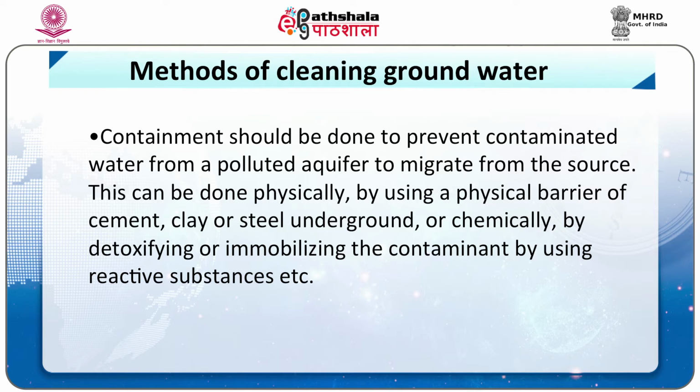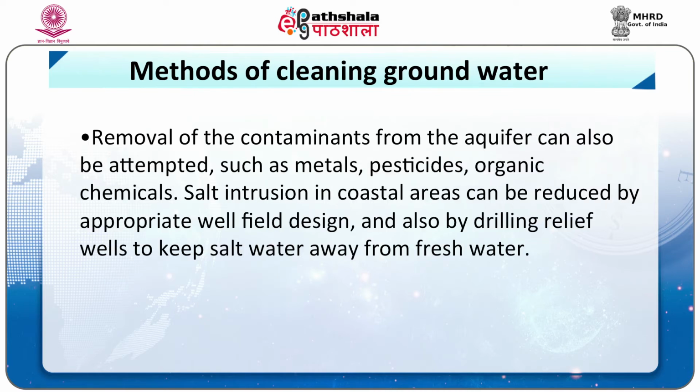Methods of cleaning groundwater. Containment should be done to prevent the contaminated water from polluted aquifers from migrating from the source. This can be done physically by using a physical barrier of cement, clay or steel underground, or chemically by detoxifying or immobilizing the contaminant by using reactive substances, etc. Removal of contaminants from the aquifer can also be attempted, such as metals, pesticides, organic chemicals.